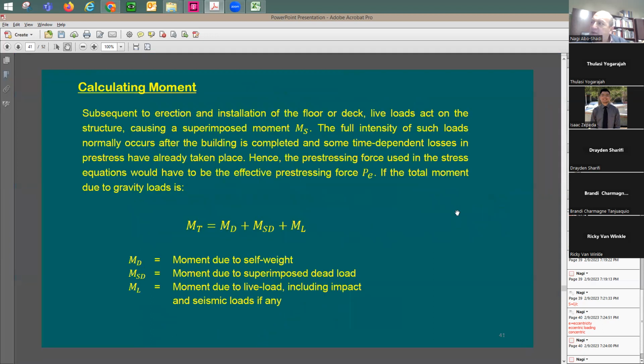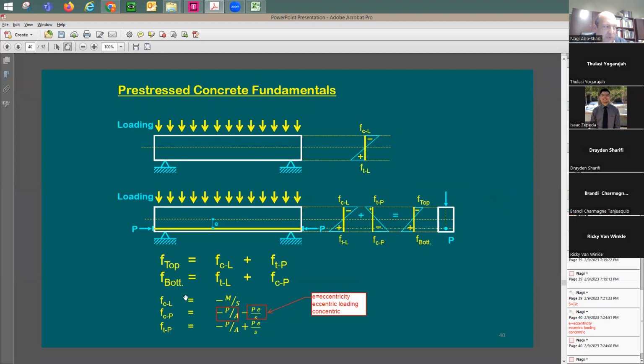Now, when it comes here to the applied, because I have two sources, right? I'm going to say you can call this 1 coming from the loading, and then you're going to have this 2 together. It's going to be the stresses coming from the pre-stressing, right? Yes, okay. Now, first the loading, this M. M is going to be the applied moment. It is not going to be P times E. P times E is going to be the eccentricity from the strands to the beam.